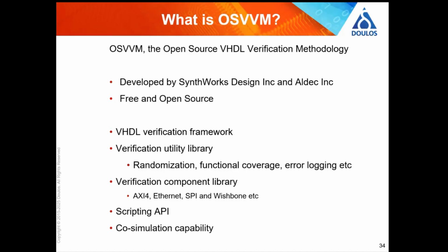You can call all of these methodologies testbench Lego, basically. So you get what is called the VHDL verification framework. Actually, that's the most Lego bit. It's how to design different pieces that fit together. So the BFMs that I was talking about earlier, that would be a driver, a monitor. How do they talk to each other? In the same way as Lego bricks fit together in a standard way, how can we design pieces of test bench that fit together in a standard way?